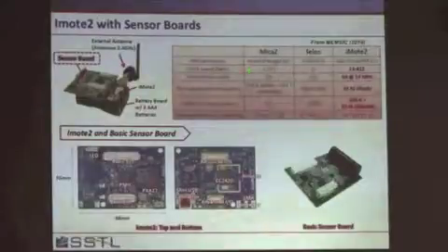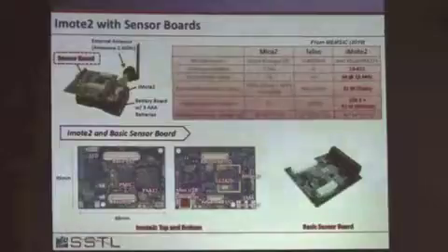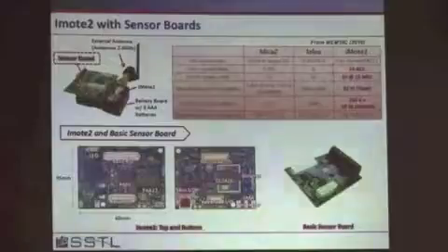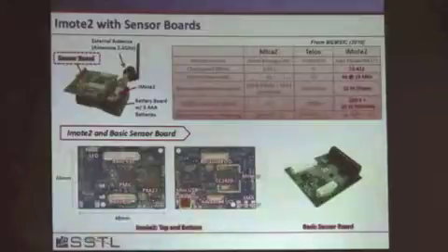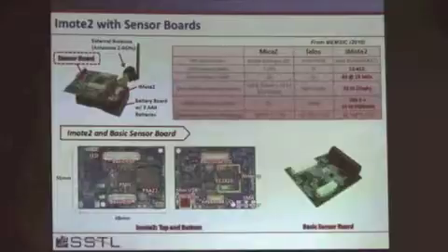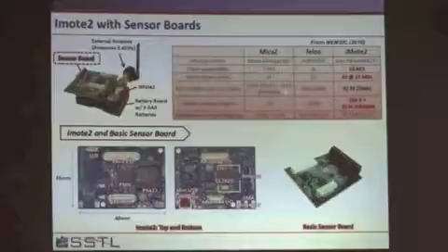I want you to look, this is the Mica Z from Berkeley, and it had a clock speed of 8 megahertz. I mean, your phones have gigahertz clock speeds now. They were trying to get low power, long battery life in these systems. If you look at the amount of memory it had, 4 kilobytes of memory. How much in the way of calculations can you do with 4 kilobytes of memory? And even the non-volatile memory for storing data, they had 100 or 512K of flash, so a half a megabyte.